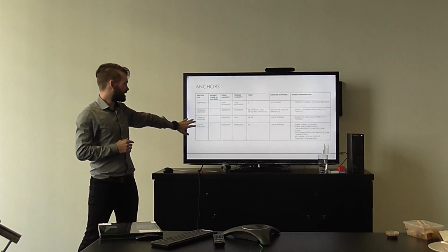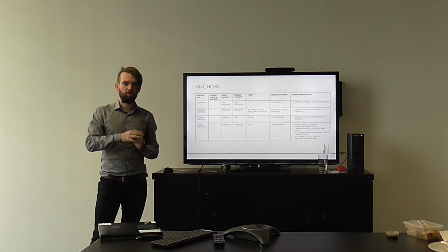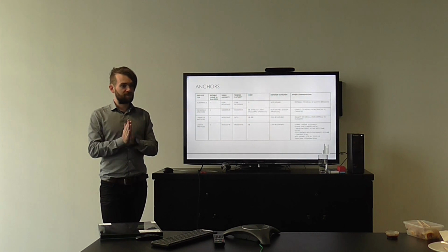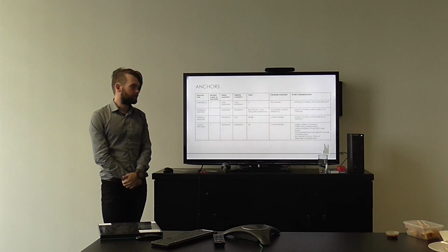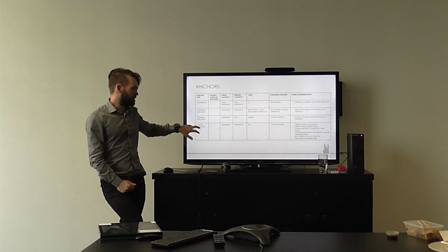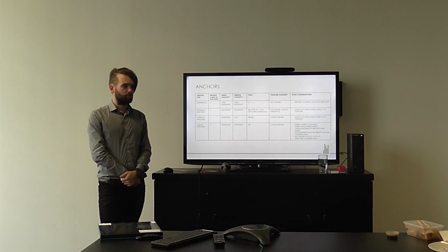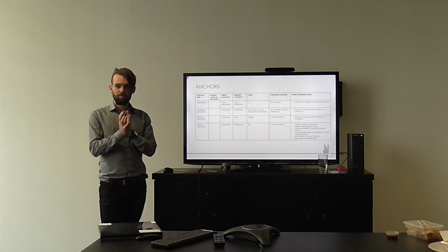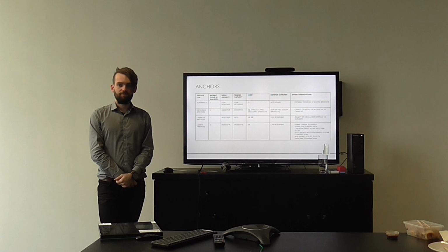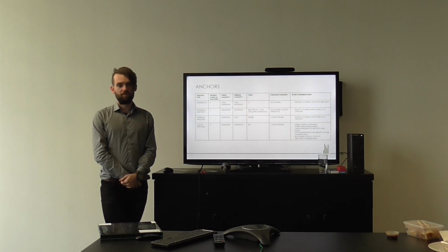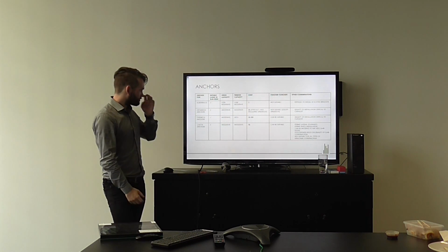Particularly screw bolts and chemical anchors, because of the way they work, whether they're just screwed in or just drilled and put in a hole, can be used quite close to a slab edge, which can be really useful, particularly in some applications where we're working with tight geometry. Unfortunately, things like our expansion anchors and casting channels are not so good at being used close to the edge of a slab, particularly the expansion anchor because of the pressure it puts within the concrete when it expands. Usually you might not be able to get that closer than maybe 50 or 60 mil from the edge of a slab, which in some situations is just not possible.